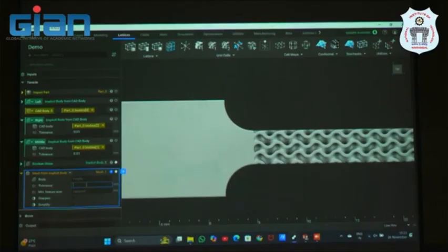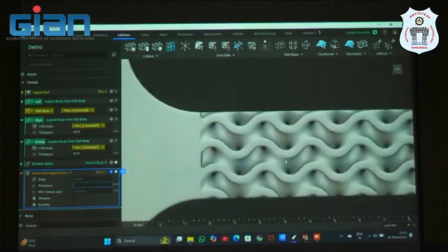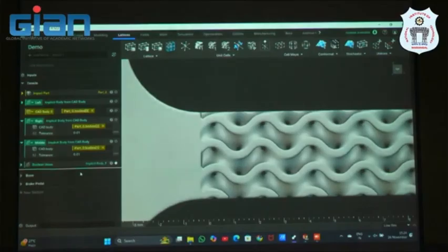And it depends on the size also. Suppose the wall thickness is 2 mm, we can go with 0.3 mm. Suppose that is 0.5 mm or something, we can go with 0.1 mm precisely. So we cannot capture the 0.5 mm thickness with a 0.5 mm tolerance, right? So that is why. So that is how one thing we can do. Any doubt till here?